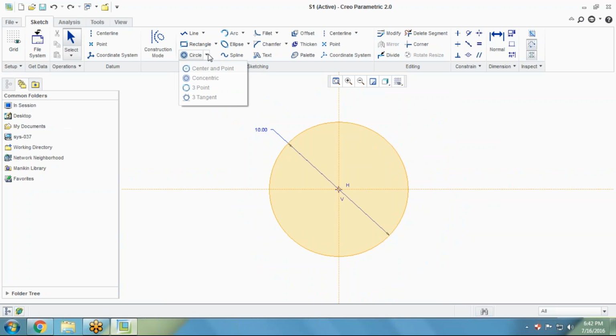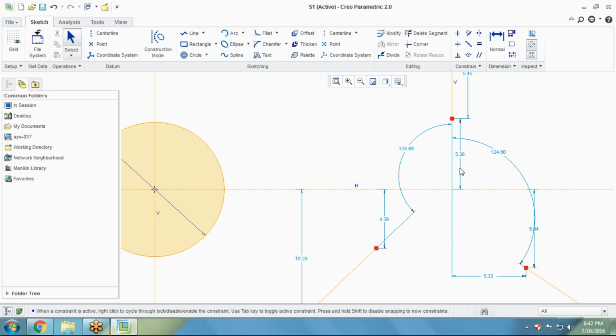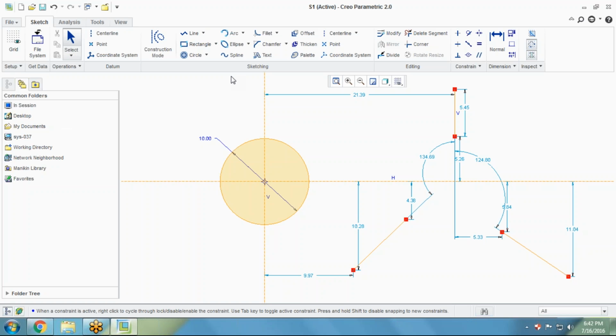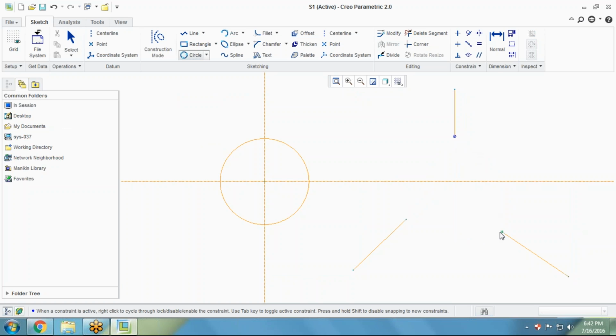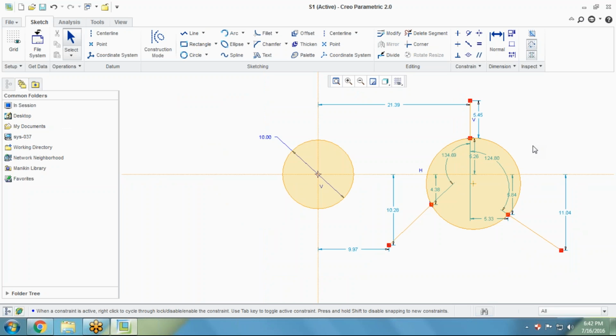Undo, and now after that we are just making a 3-point circle. And what is the utility of the 3-point circle? Basically, we can utilize this option when we know the 3 points' positions, and I only need to provide the position there, because I don't need to give the radius. So we are just giving the 3-point circle. One is this, second is this, third one is this.